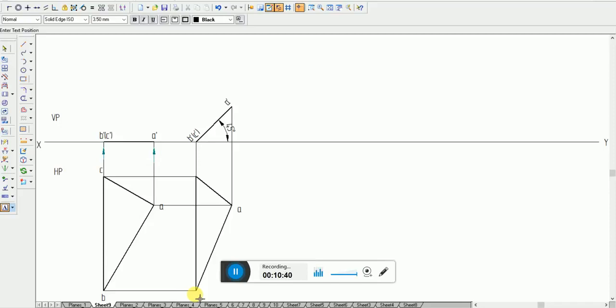So I'll just name the points back. Now again put the arrows. Now the arrows are downward arrows. The reason is you are projecting the lamina from VP to HP, and in the first case you were projecting from HP to VP. That is, this lamina was drawn first, next this projection was drawn later, but here this lamina is projected first, then it is drawn. Okay, so therefore that way. And always try to have these arrow marks properly aligned because it looks neat.